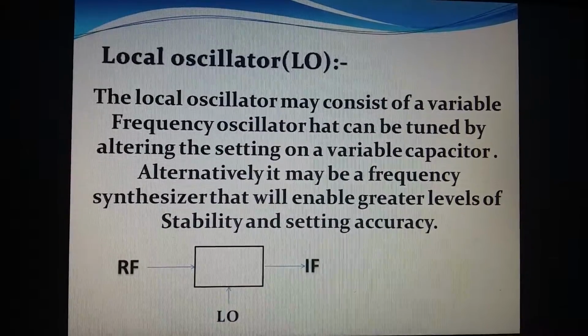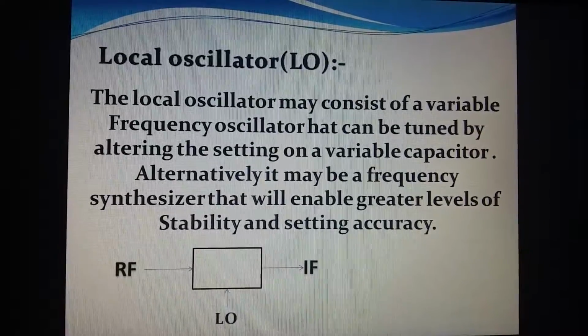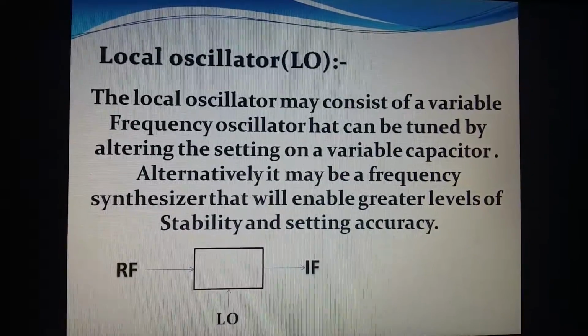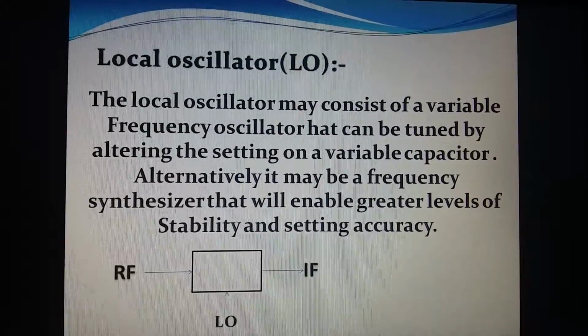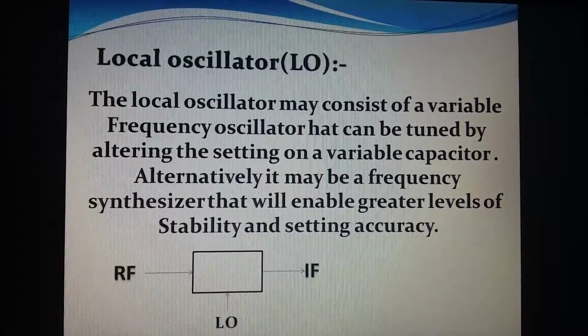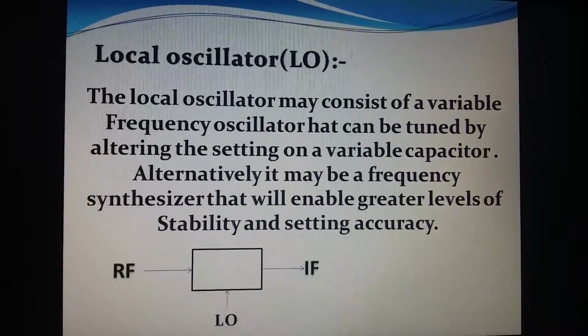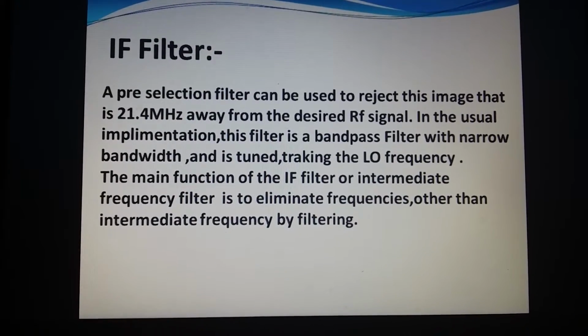The local oscillator may consist of a variable frequency oscillator that can be tuned by altering the setting on a variable capacitor. Alternatively, it may be a frequency synthesizer that will enable greater levels of stability and setting accuracy. Now I will explain about the IF filter.